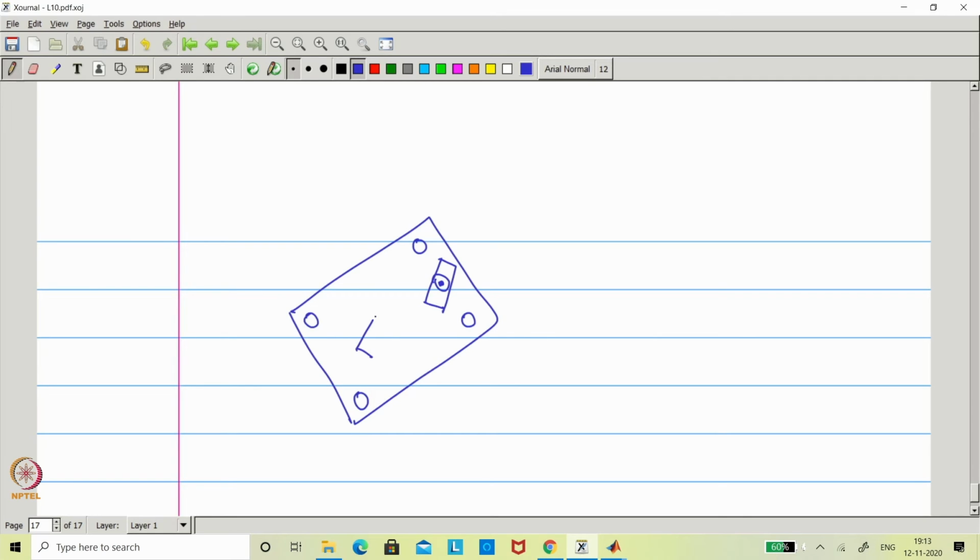Similarly, I am taking this wheel. There are two wheels which are powered and rotatable, in the sense that you can see this theta 2 and this theta 1 are playable. This wheel gives A1 and omega 1, and this one gives A2 and omega 2. I can decompose them into x and y.